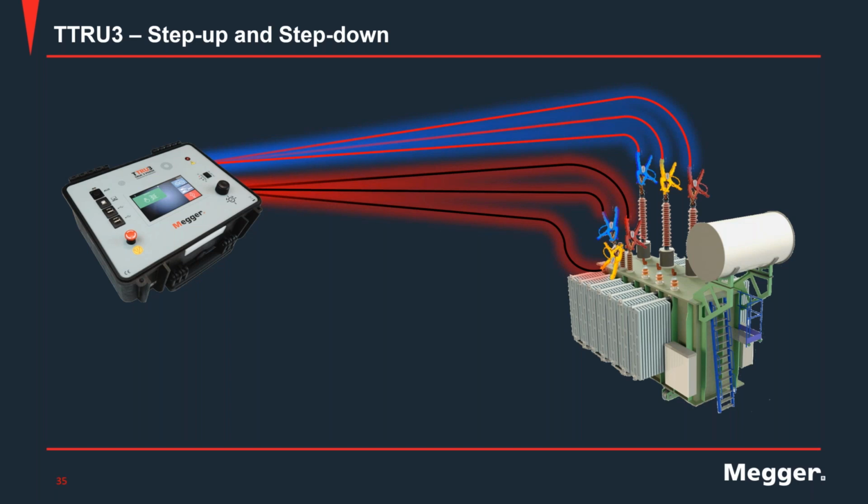As you can see, I'm going to go back, right? My red glow is indicating which side of the transformer is being energized. This is the traditional way, step down. When I go to step up, I'm energizing the low voltage side of the unit. And remember, every transformer will show some voltage dependency, some obviously with a higher degree than others. And this has to do with the core material, the windings, type, and construction, right?